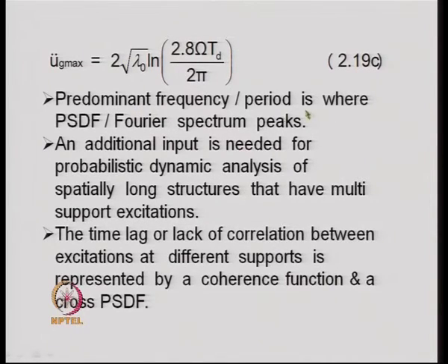Predominant frequency or period is where the PSDF and Fourier spectrum peak. An additional input is needed for probabilistic dynamic analysis of spatially long structures that have multi-support excitation. The time lag or lack of correlation between excitations at different supports is represented by a coherence function and a cross PSDF function.